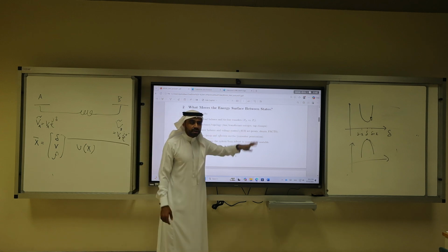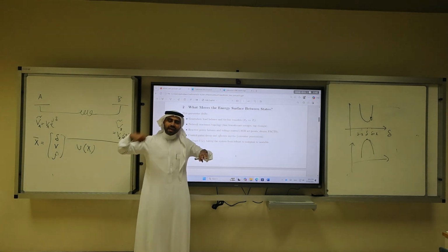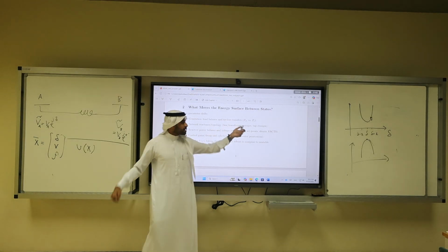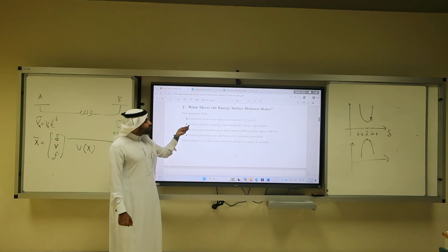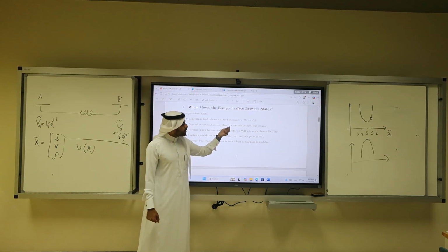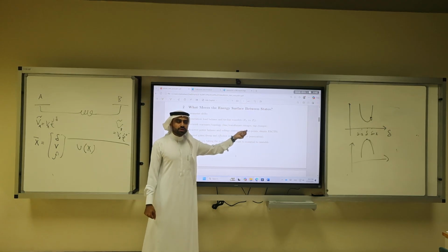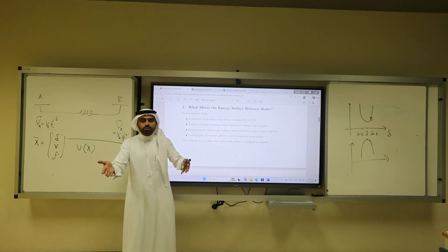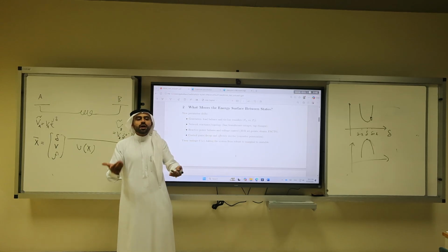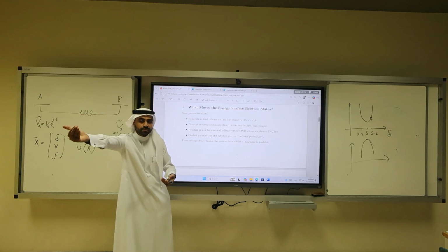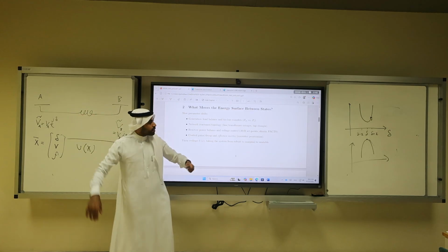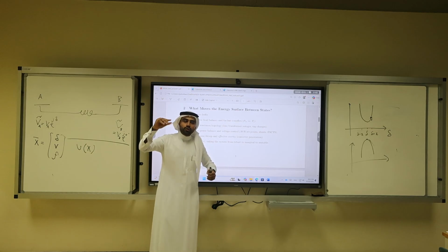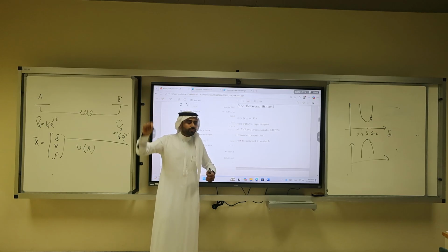What that means is, if I'm putting in more mechanical power, PM, how would this change the electrical power? If I change the topology, if I have transformer outages, if I have a transmission line contingency, if this line is out of service, how would this impact the stability of my system? Even if I change the ratio of a transformer from 1.09 to 1.05, what will happen?